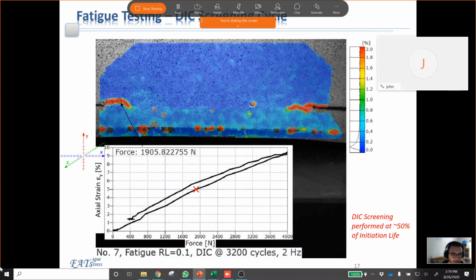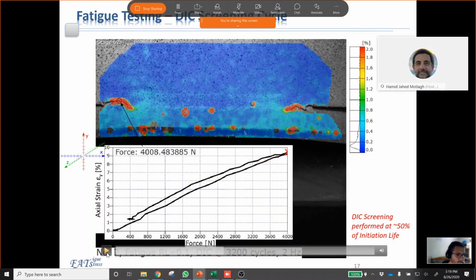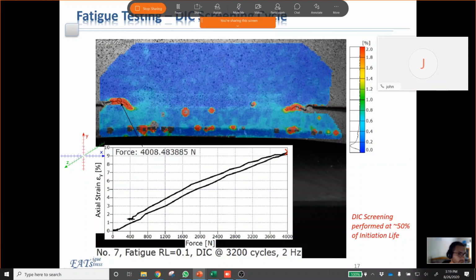So the size of the real part, the two mating parts, is it more like this 0.7 millimeter to 1? It depends on where on the vehicle it is. Typically on the wide body, the thicknesses are a lot lower. But if it is used on suspension components like stampings or the subframe, it is more like 2.6.